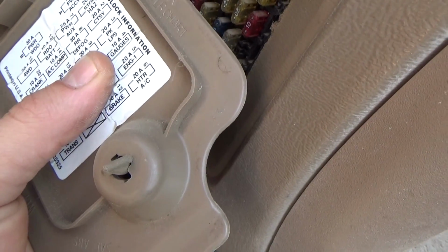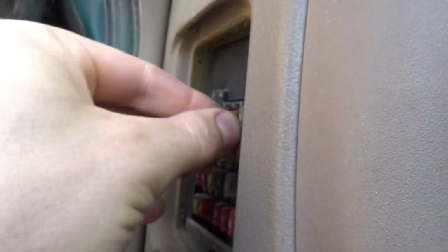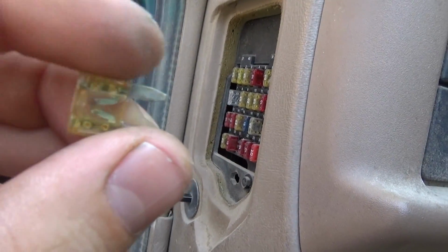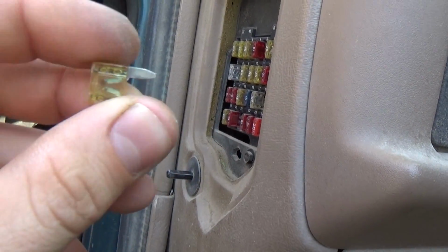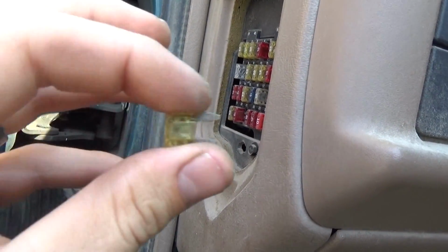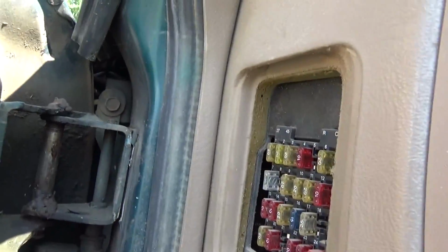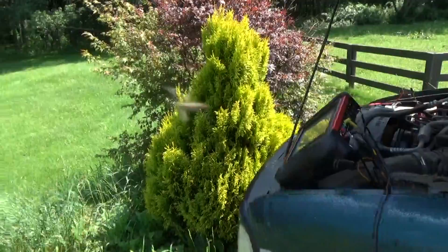And it should be a 20 ampere, that guy right there. And yes, indeed, it is blown. Fantastic. Now the question is, why did this happen? Does this look familiar? Heat and vibration. We might have to go down to these oxygen sensors and take a look.